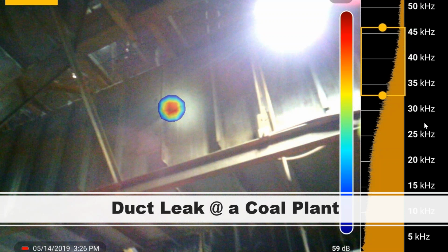Okay, next one. How have you seen this used at a power plant? I understand that it can find instrument air line leaks, but I'm interested if you have tried it on HRSG penetrations. Also, a leaking valve produces internal ultrasound frequencies. Is this able to pick up internal leaks? I'd be interested in a demo, like for a day at the power plant. So this is one specific customer who asked a couple questions. But yeah, I haven't actually tested that. Once again, I recommend that you get a demo and try it. As far as internal leaks, it depends on how large the leak is.